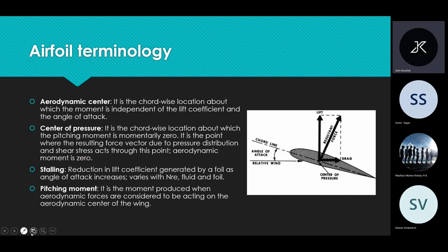So what is written here is that this is the total resultant force, and this is the center of pressure. But if we take moment at any other point, like here, this force will be acting on this point and also a moment that is given by F into this distance. Similarly, if we take moment here, we will get this force and the torque moment also, given by F into this distance.